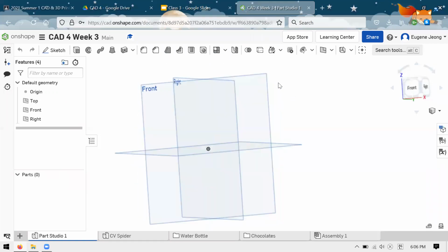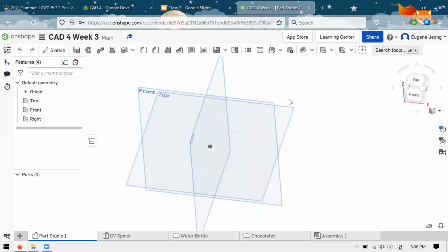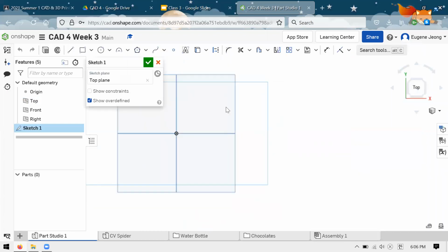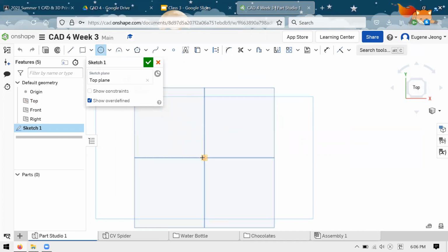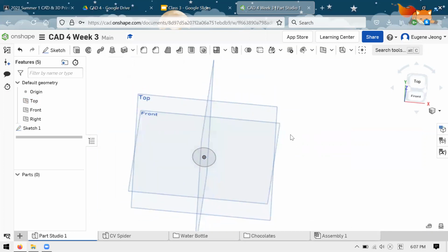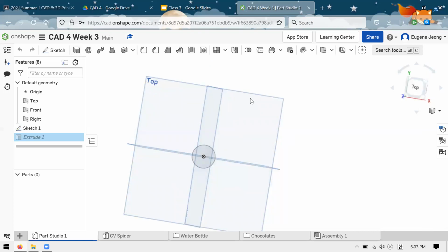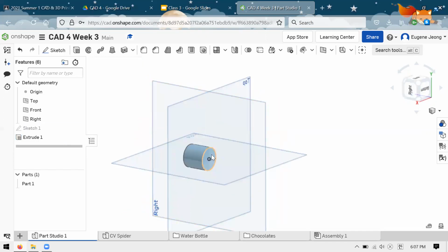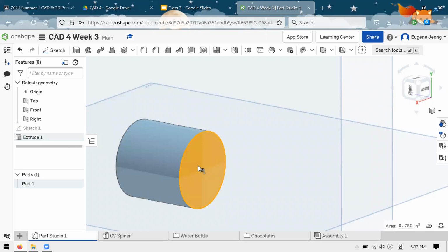All right, so to motivate the first thing that we'll be talking about, I'll start by talking a bit about sketches. So usually when you start making a model, you start with a sketch. And what you'll notice is that all sketches have to be done in a plane. It even says so in this little window. It asks you to select a sketch plane. And so no matter what I do, just from a single sketch and extrude, I'm always going to end up with a bit of a flat surface here because I started off with a sketch that's in a plane.